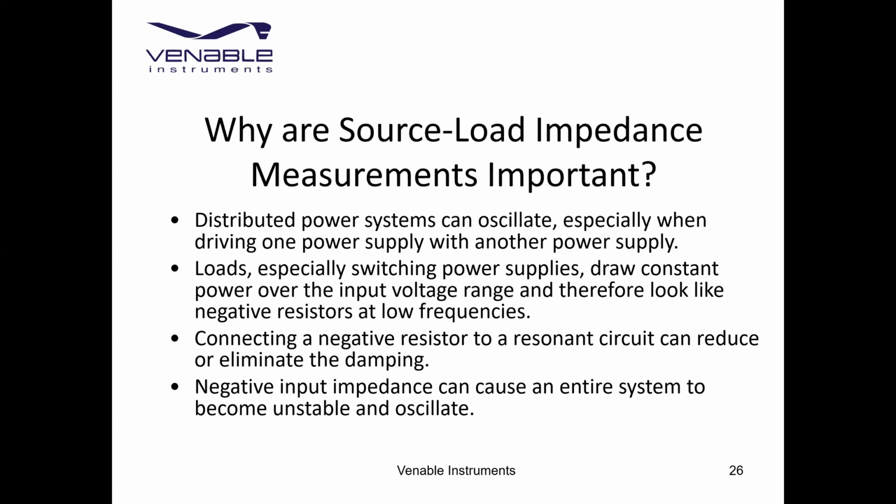This is an explanation of what happens: most power supplies, or switching power supplies, are constant power devices. So they act like an incremental negative resistor, especially at low frequencies, and that negative resistance can cancel out any type of damping that you may have in your circuit and cause it to oscillate.